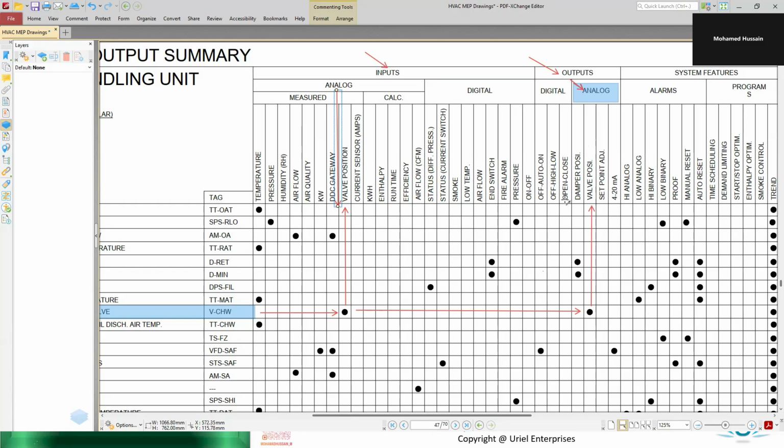So we started with, we need an AHU valve, and we started by looking at the MEP drawing. We locate the AHU schedule, the equipment schedule. In that we look at the cooling coil portion. We understand what type of medium, water medium, and later on we look at the detailed drawing. We understand the valve pattern.